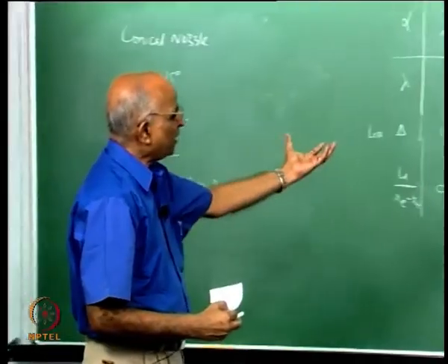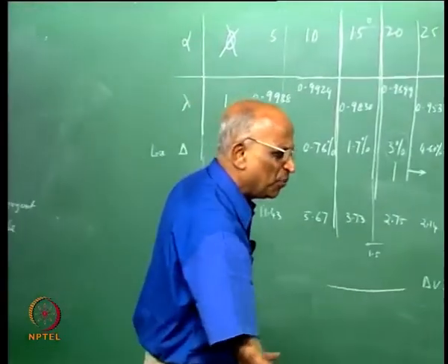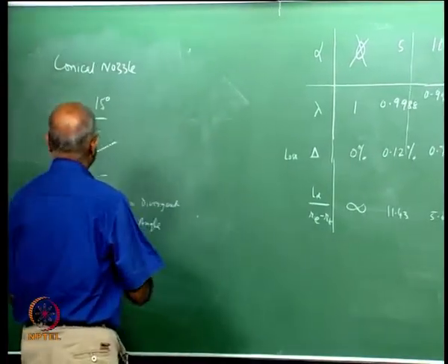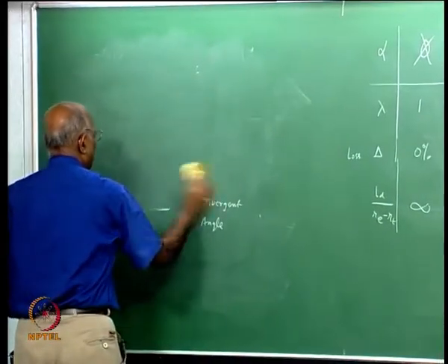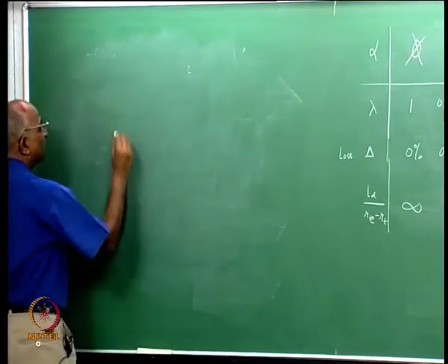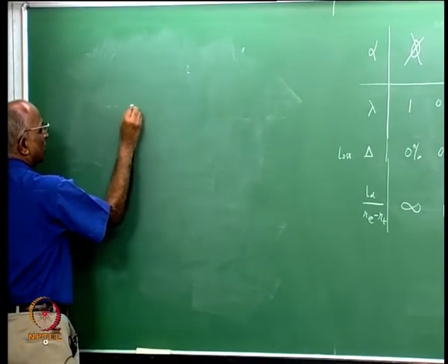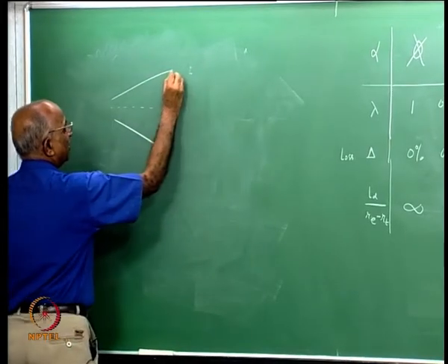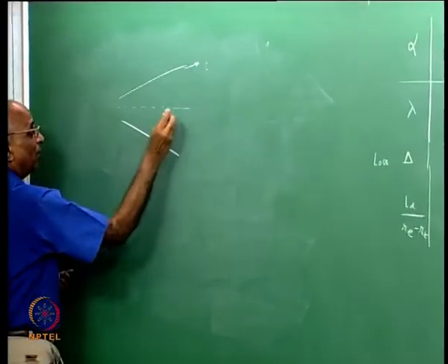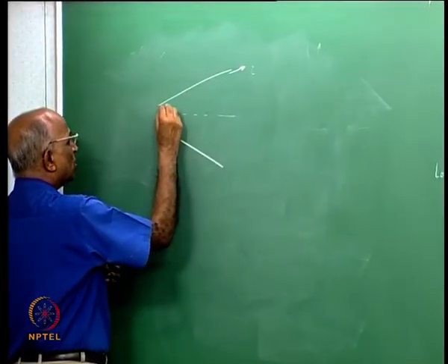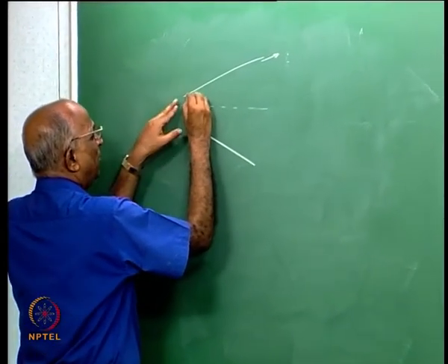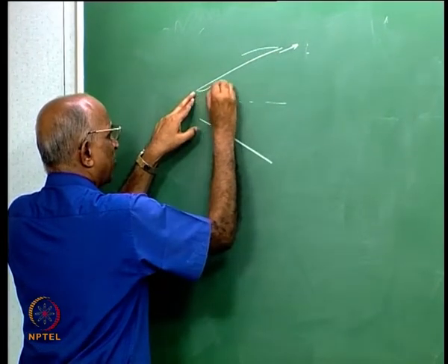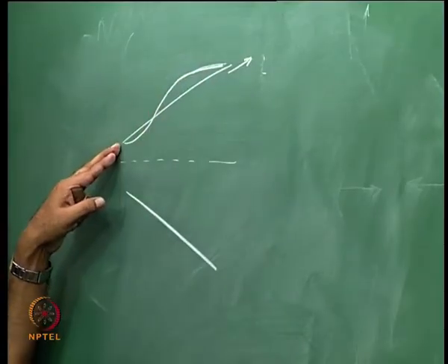Now, if this part is clear, I just have a few more things to tell in a nozzle. The question is, why did we address this divergence problem in such a critical way? For instance, we told ourselves, well, your nozzle is something like this, divergent, and you are interested in this angle being alpha, you do not want to lose thrust. What prevents us from having a nozzle which I can initially expand out and bring back like this?